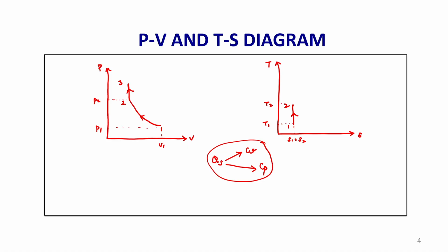So, in dual cycle, or combustion cycle, heat is added first at constant volume. A partial amount of heat is added at constant volume and the remaining heat is added at constant pressure. So, 2 to 3 and 3 to 4, constant pressure is a line perpendicular to the y axis. During both these processes, Qs is the amount of heat supplied. Here this is constant volume heat addition and this is constant pressure heat addition. This is 2 to 3, this is 3 to 4.